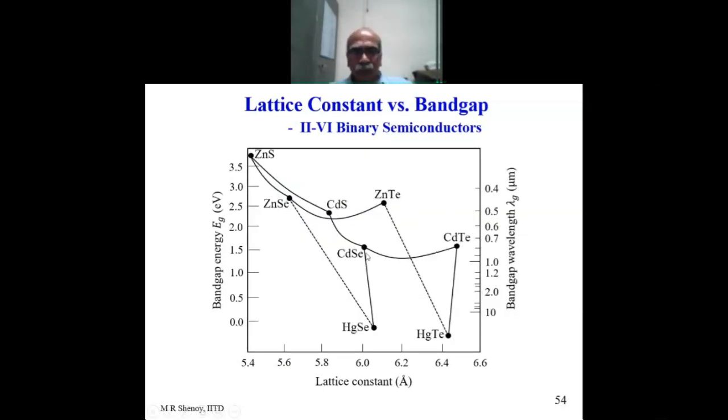Finally, I want to show that there are other materials, particularly this material, cadmium telluride and mercury telluride here, have almost similar lattice constant, almost on the vertical line. And therefore, mercury cadmium telluride was a material and is a material which is widely used for this wavelength range. See that this is the infrared. The defense people always have used this mercury cadmium telluride in the near infrared. It's a very good detector which is used widely for the near IR.